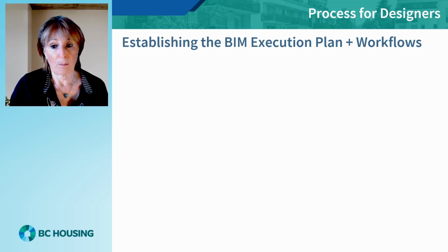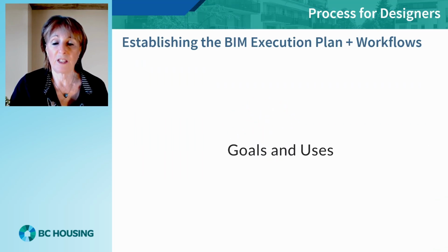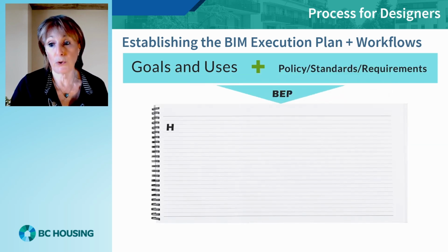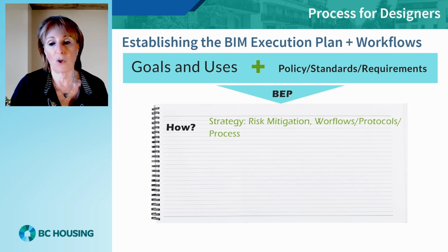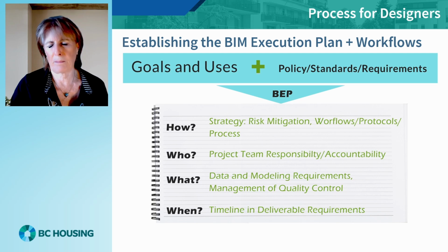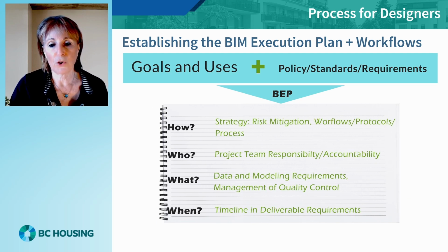The BIM execution plan is the project document where the design team records their proposed strategies and workflows that they will use to achieve the goals established in the BIM requirements by the owner. The design team is responsible for defining who is going to do what, when, and how to achieve the specified goals. What are the workflows and protocols that are going to be used? Which team is going to be responsible for what data and modelling requirements? And when will the information be available? What is the timeline?